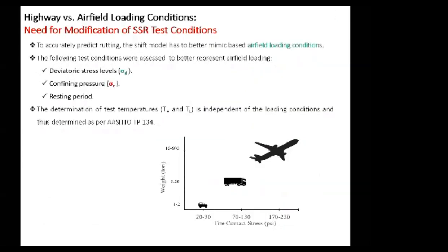Now, I was discussing with Dr. Richard Kim about these values, and Dr. Kim said, you know what, let's bring the loading regime that we apply in the SSR test a bit higher, because the stresses that are passed down to the pavement by the gears of the airplane are higher than the stresses we are testing the mix at to develop the model. So, optimally, you would like to test the mixture and develop the model using stresses that are close to those in reality that are going to be applied.